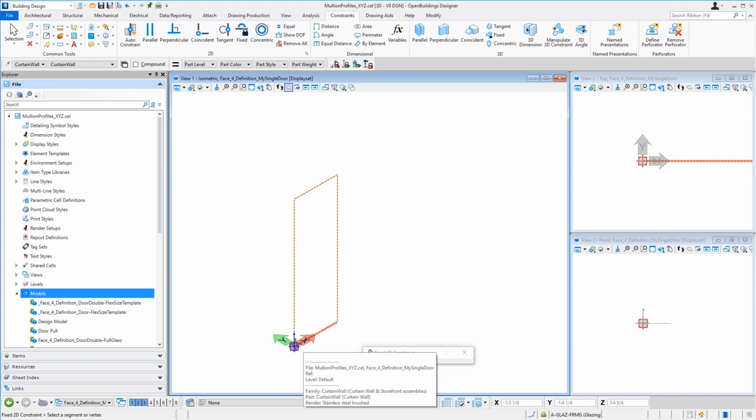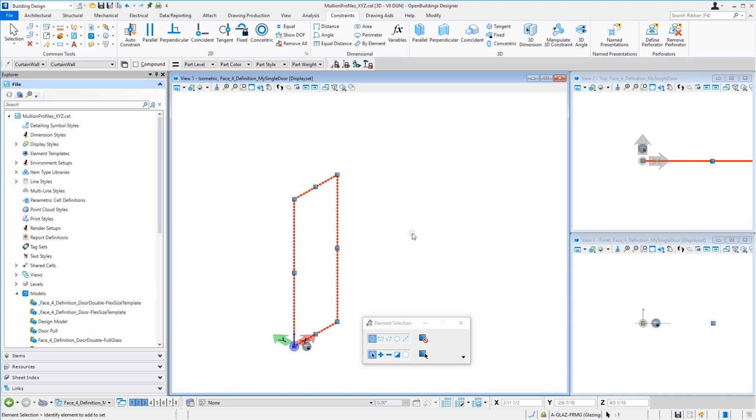And you'll see that little red crosshair indicates I'm at the vertice, and left click to accept it, and we can see that fixed constraint there. And what that means is if I were to select that rectangle and I have handles, right, I could move this edge, but if I try and move this edge, it won't move because it's been fixed.